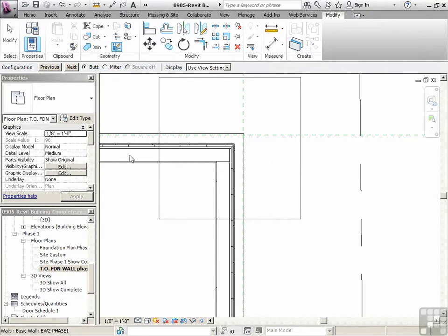It's basically saying, okay, you're working on that corner, and it gives you some little lines showing what type of condition you have. So essentially what's happening is we're building this wall and then we're building this wall to there. So this wall, even the brick, is part of this wall right here where my mouse is. Now you can change that. So I can say, give me the next version of, we could say, let's use a miter joint. Okay, and if there's different possibilities, you can do that.